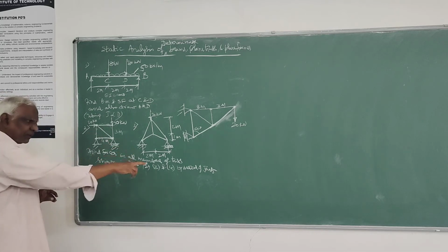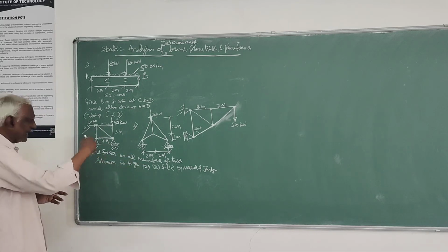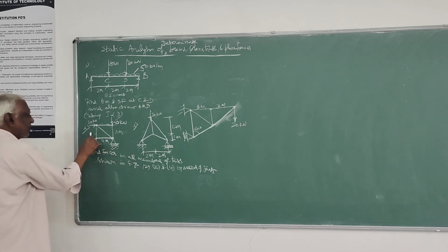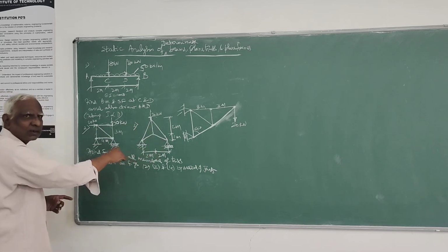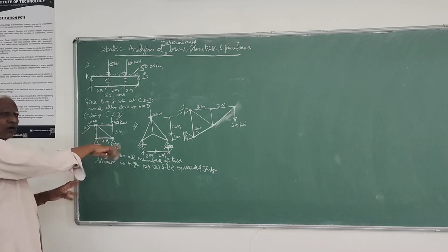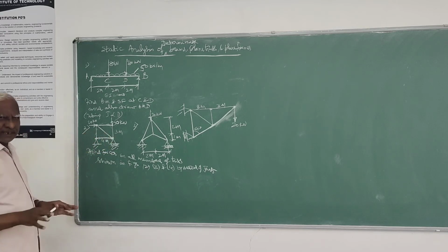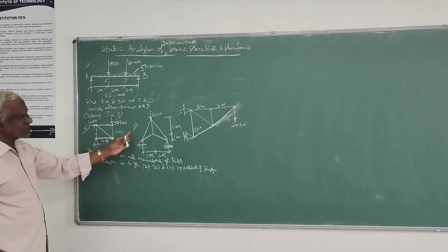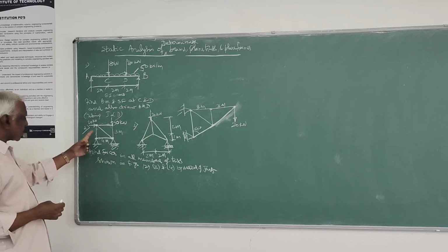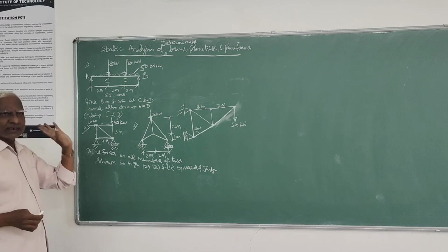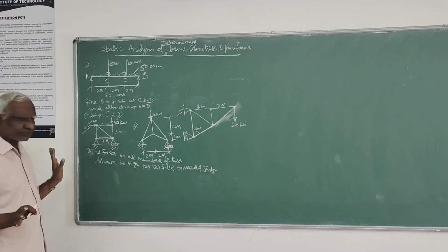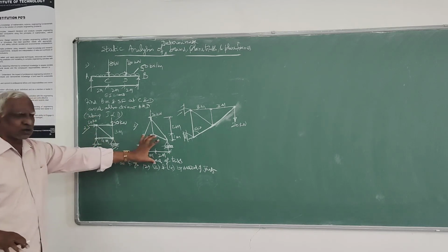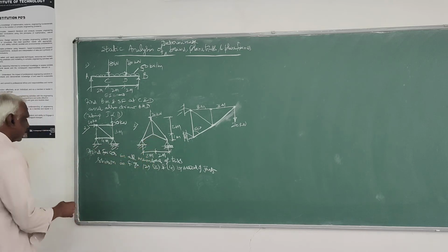After drawing the free body diagram and evaluating, if the value is negative, then in one more sketch you show that arrow in the opposite direction, otherwise retain it. So go on entering the forces with the correct arrow in one more sketch. But to start with, always take tension. So that's all the procedure you have to follow. This is what is taken.